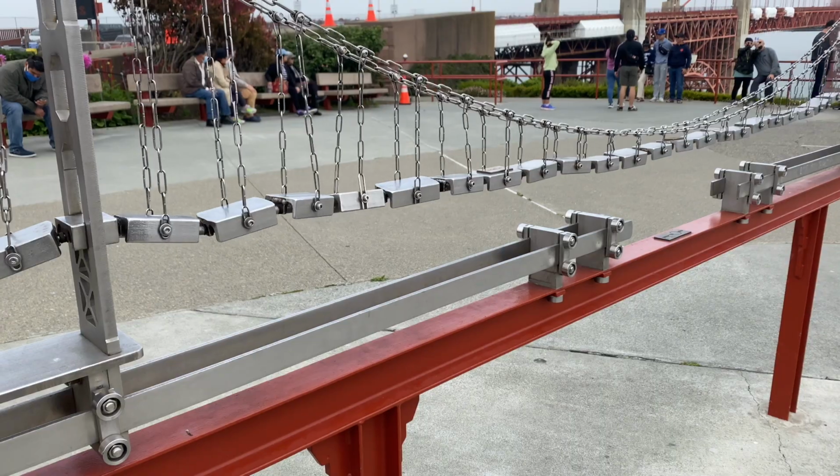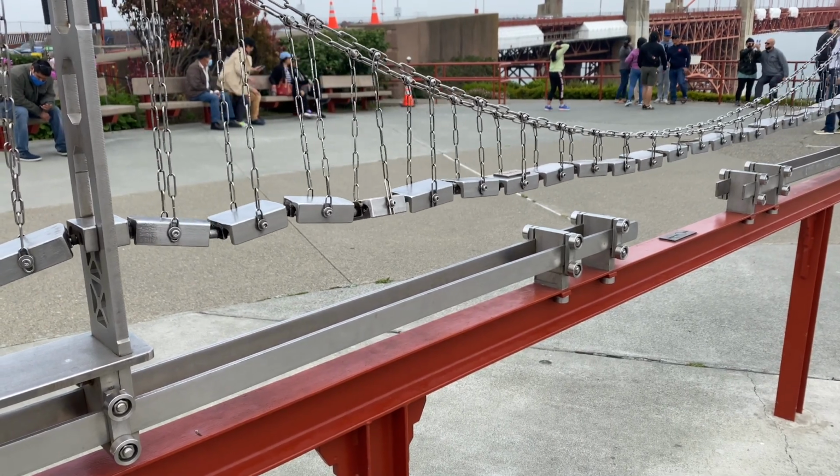And what this means is, when we have higher supports, the tension is less, so the cables don't need to be as strong, and we can get the materials cheaper. But the trade-off here is that the higher supports will cost extra. So engineers designing suspension bridges have to do a mathematical analysis to determine what is the optimal bridge height to minimize the cost. Most suspension bridges are made by taking small deck sections and chaining them together, like shown in this model.